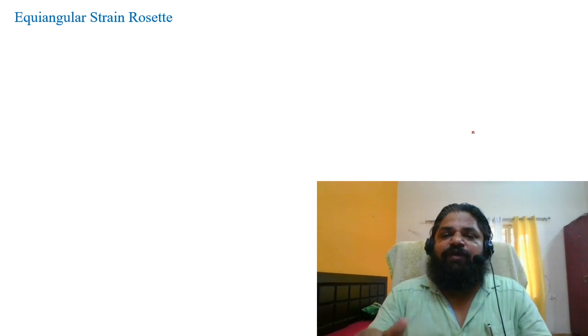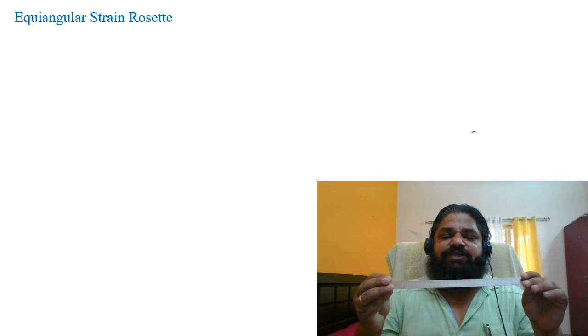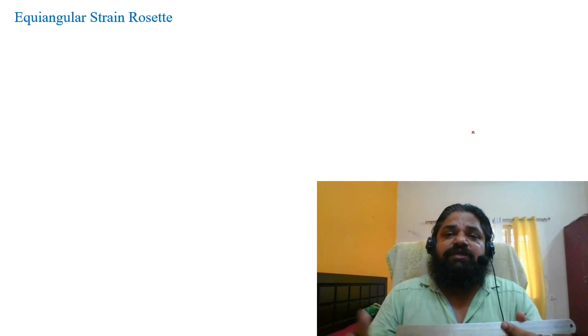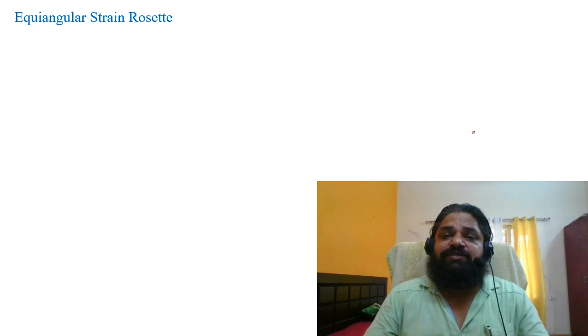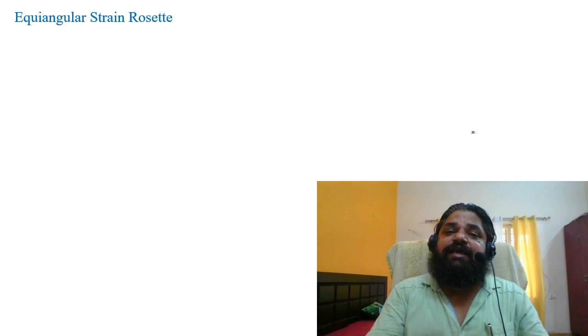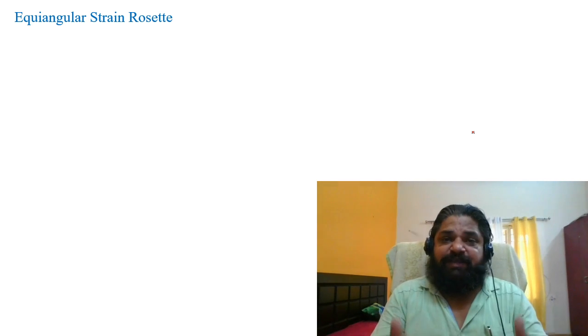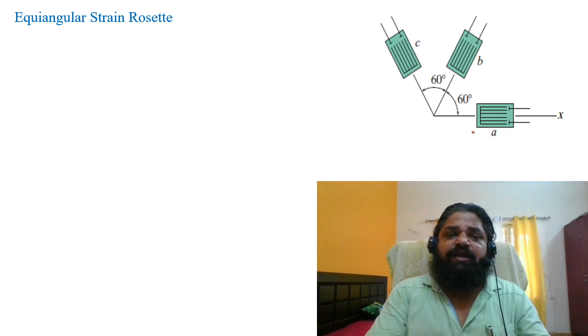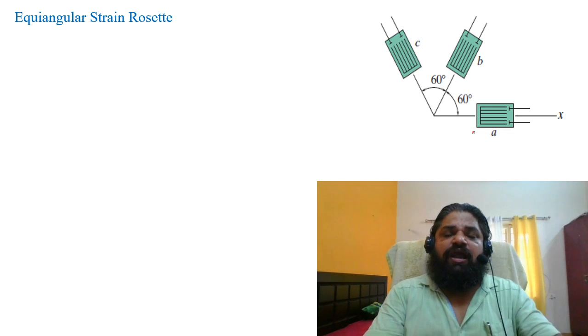If I know the strains, then I multiply with E, whether it is mild steel, high speed steel or cast iron, I know the value of E, and I can get the stresses. Similarly, the equiangular strain rosette. I also talked about 60, 60, 60. Strain rosettes are classified based on the angles or the placing. One is rectangular, one is equiangular, with a spacing of 60, 60, 60, or it can be 120. You can see different arrangements in different books.